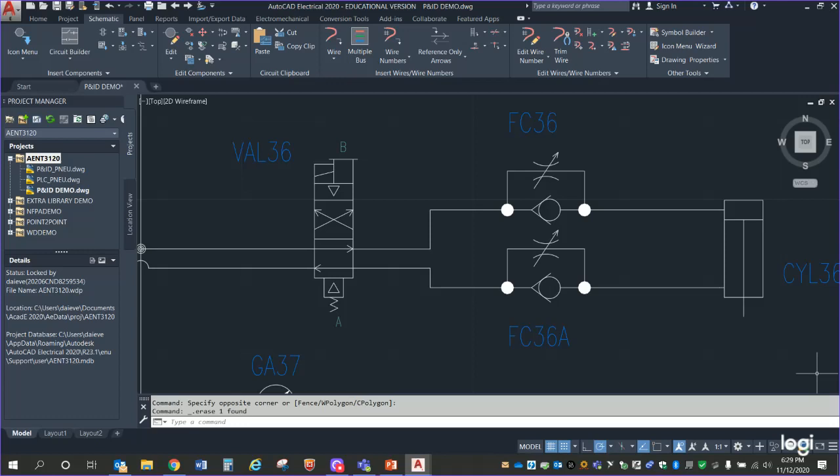What could be wrong? Yeah, the cylinder could be bound up. It could be clogged up like we were talking about earlier. Could the air compressor be down? Have you ever walked through our machine shop down here on a day the air compressor's down? It's like Christmas down there. It's red and green lights everywhere, and it's more red than green, okay? Because every one of those CNC machines automatically goes into an alarm condition because nothing can work. Your tool changers can't work. Everything's down. Same's going to happen here.